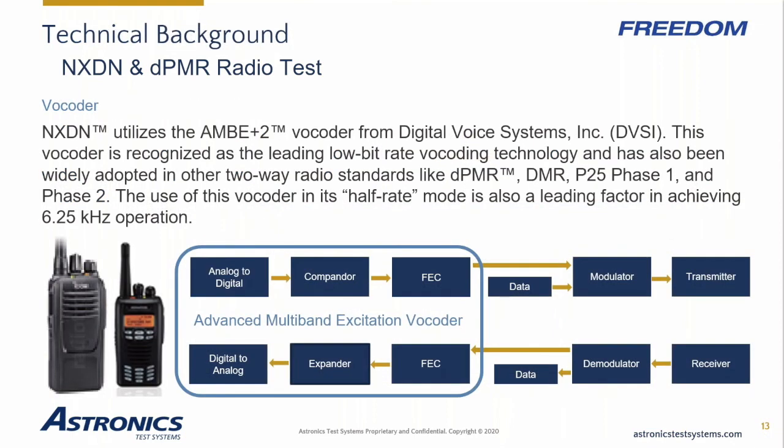On this screen, you can see a block diagram of the transmission from the transmission point to the receiving end. That's the job of the vocoder, which is what we're going to talk about in this slide. The vocoder uses a complex algorithm that breaks down the human voice using an ingenious model of human speech. As you can see on the block diagram, the first part of the process is analog to digital conversion, which turns the voltage levels into their digital values.